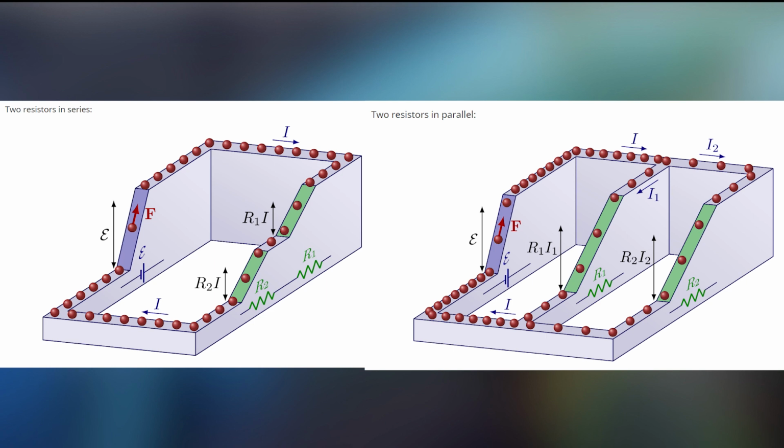And also what you'll see is that each globe is just as bright as a single globe was if you only had one globe hooked up. And that's because the potential difference is actually the same. The potential difference over each of your globes is going to be 6 volts. Because remember, your electrons are going through the path separately.